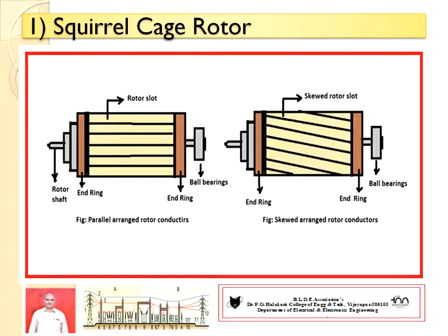95% of industrial applications are met by the squirrel cage type of rotor because it has many advantages. It has simple construction, more mechanically rugged construction, high efficiency, high power factor. Its starting arrangement is simple. It develops a moderate torque. All things are favorable. That's why 95% of industrial applications are met by the squirrel cage type of rotor.